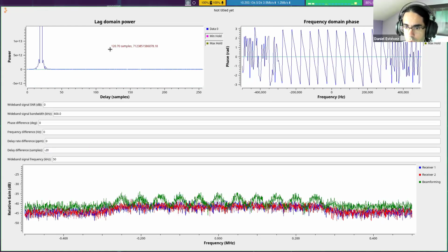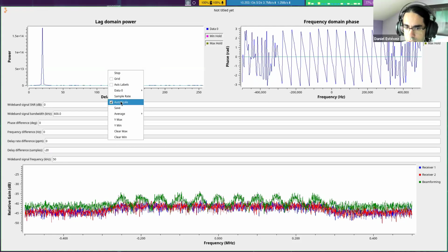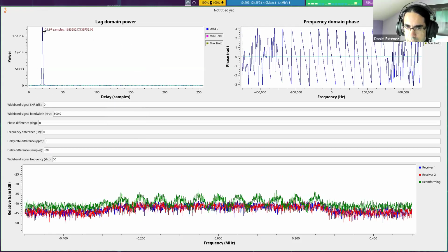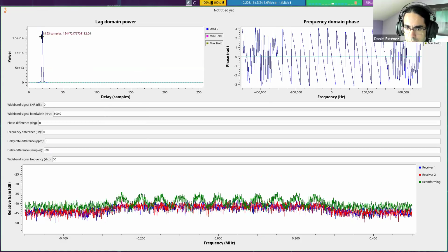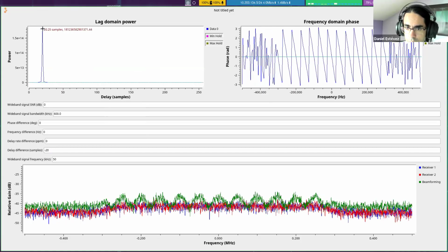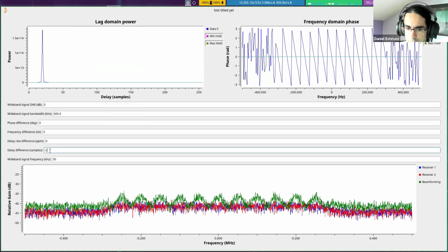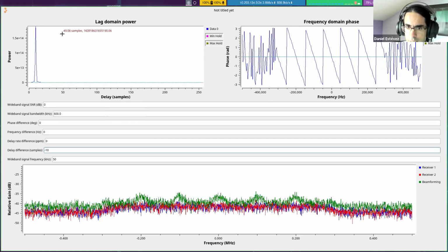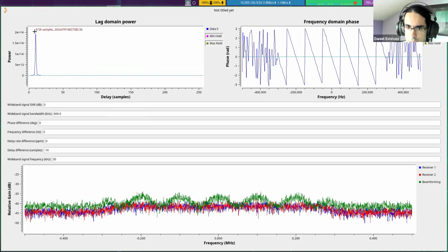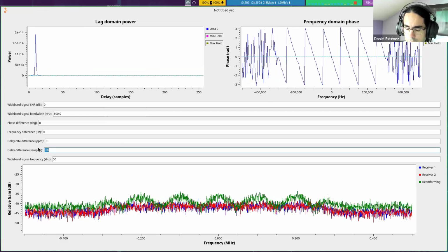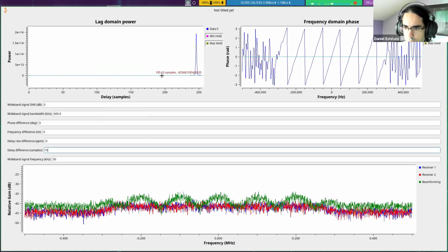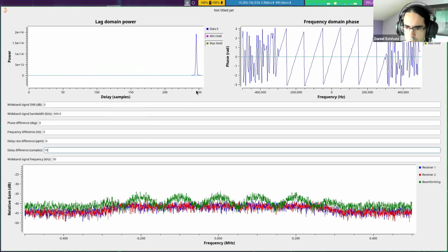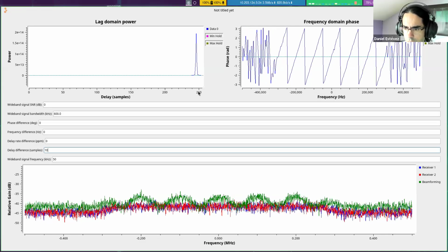And also the whole reason I put the FFT in here is because, again, there is a sign convention at play. My peak is at 20 samples. If I go to, I don't know, minus 10, now my peak is at minus 10 samples. And if I put 10 here, it goes to the other side. And this all needs to be interpreted with some care regarding signs.